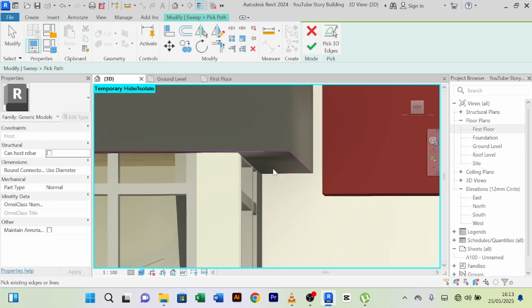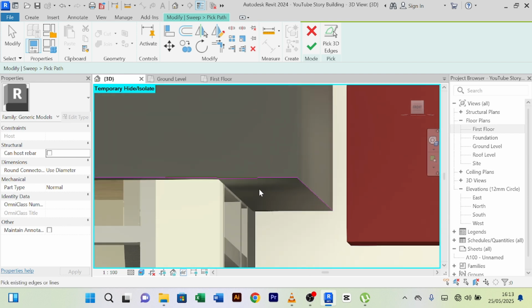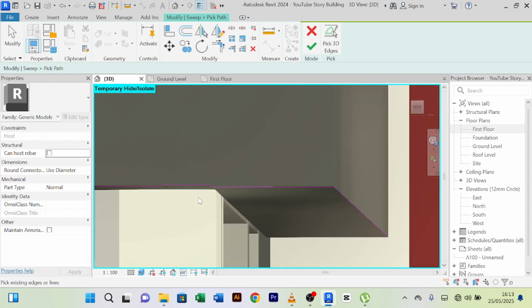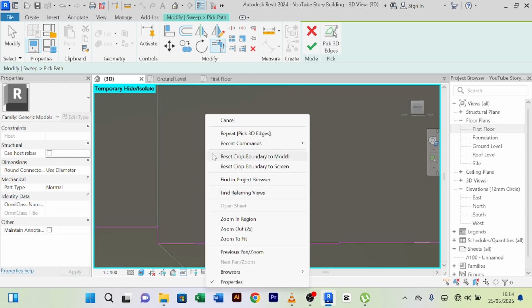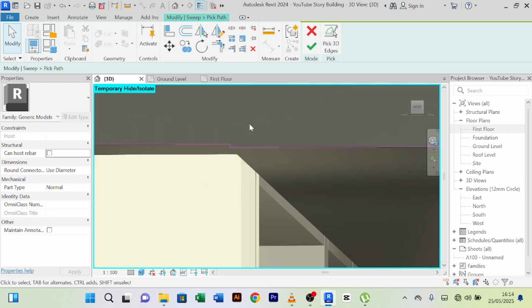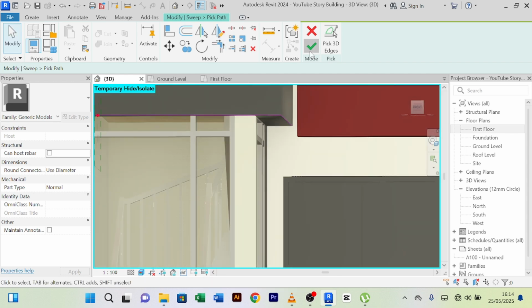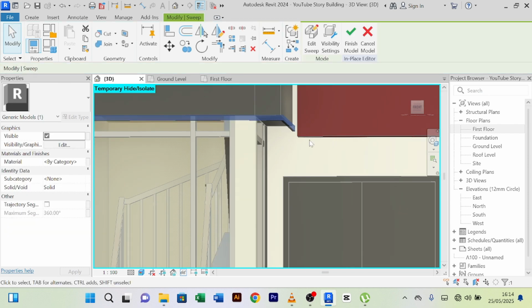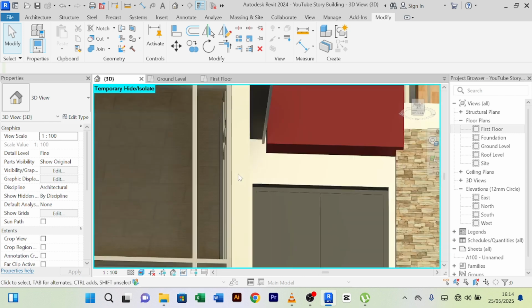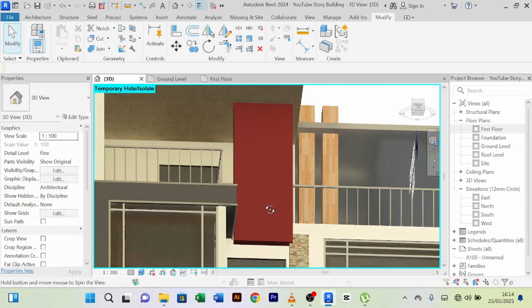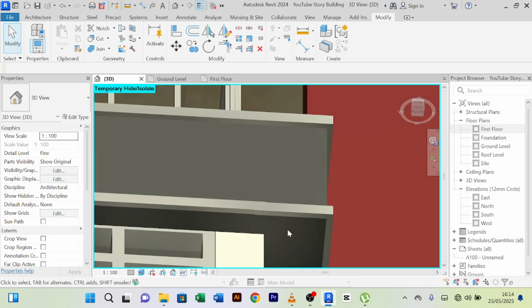So now this extrusion is sitting, this extrusion are not sitting exactly the same way. That's why this sweep is saying there are two loops. But you can pick this side, this one, then you trim this to this. We're going to fix that extrusion. And then if we click OK, it will be able to finish it. Now it is okay, but still we have to fix this extrusion. We are going to align them properly so that they don't give us such loops.